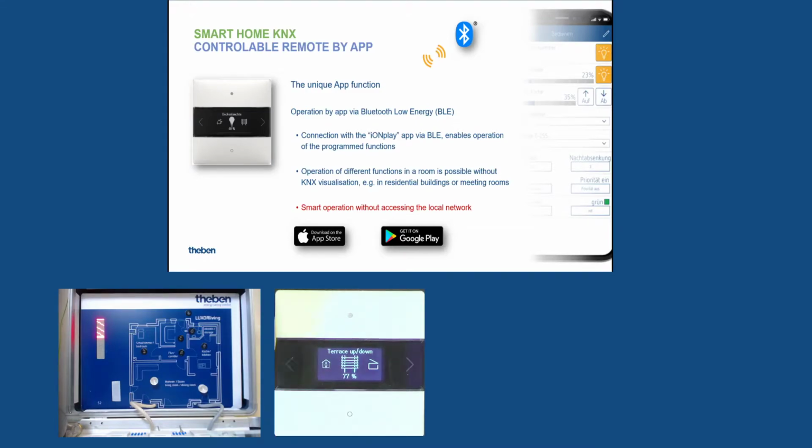So you see here my fingers popping up. With left and right, you can swap through the different applications which have been programmed from the ETS side. I leave it here, sofa area, so it's dimming. If you press here slightly, the dimming light in our sofa area, in our relax area, should pop up now, and with the off command here we stop it.